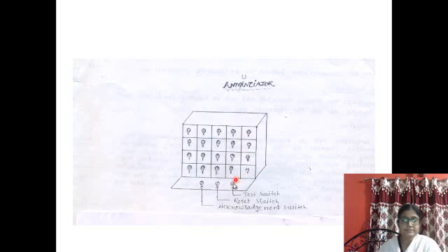There are only three switches. One is the test switch, another is the reset switch, and this one is the acknowledgement switch. The acknowledgement switch is for when any failure occurs: the corresponding lamp will glow and the sound will be produced, so the audio and visual signals are produced for that particular channel, and the plant personnel will press the acknowledgement switch.